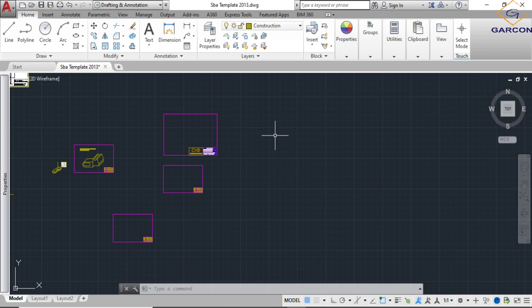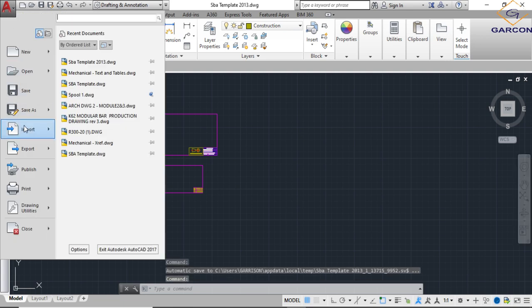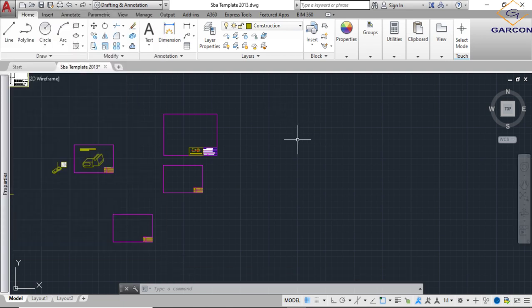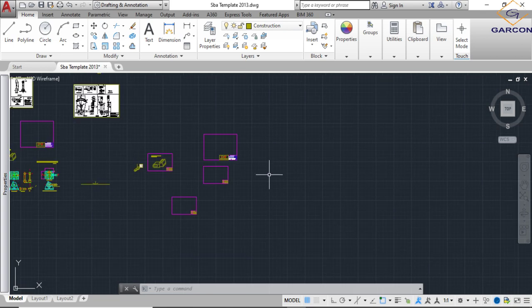At this stage, make sure your drawing is saved as your full name and your class. You want to make sure that you set up your layers. You go to layer properties and set up your different layers: phantom line, object line. If you have not done this, you can check back to the classroom on Google. You will see all the information there. Set the limits and your units. Now after you set up your drawing sheet, you're ready to do some drawing.